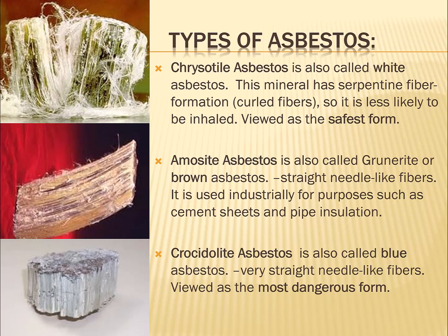And remember, silica is the most common mineral across the face of the earth. It's everywhere. It's in the gravel and the sand, and it's in the Portland cement of concrete. And so when you saw cut concrete, you're getting a freebase, pure version of silica. Very dangerous to breathe that stuff, and people breathe it all the time. It's in many forms of drywall. The asbestos is in some of the forms of drywall, and there's silica in drywall.